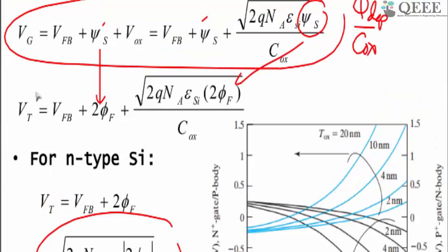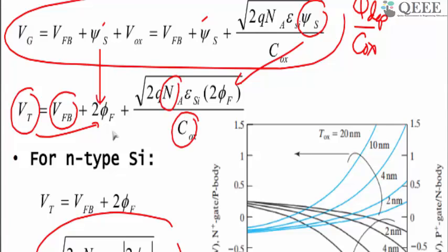You can see the Vt depends on material parameters. Let us look at what Vt depends upon. One is phi f, the amount of band bending, which is also a material parameter, but then it depends upon doping and it depends upon oxide thickness. If you are a process or device engineer, you cannot change the electron affinity of a material, but the doping concentration and the oxide capacitance, because this depends upon Tox, the thickness of the oxide, are under your control.